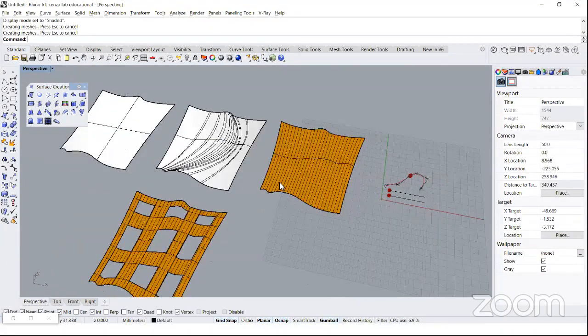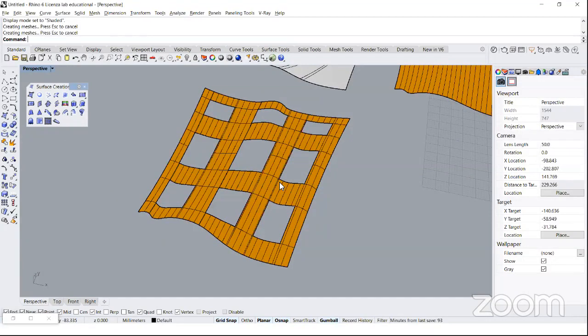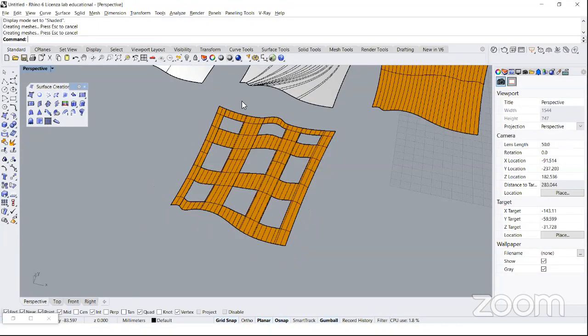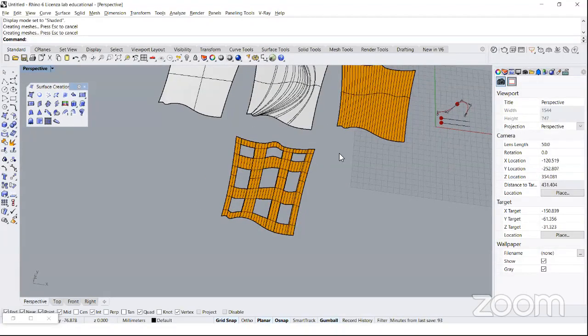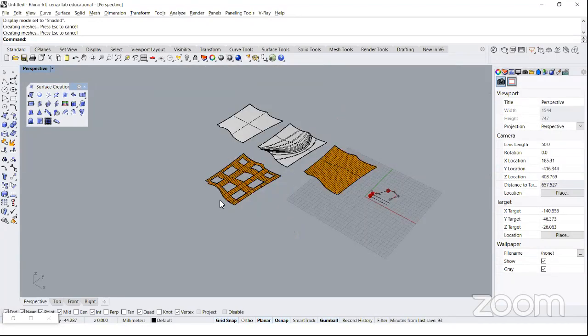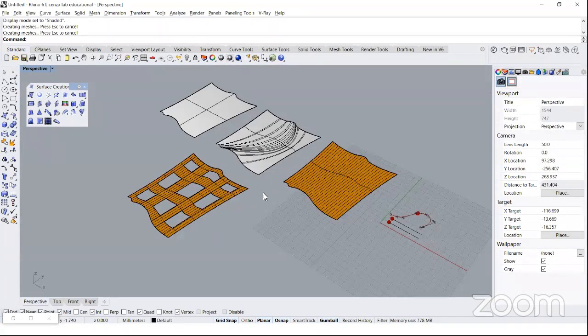One last consideration that I would like to do about controlling NURBS topology is this. You see that my surfaces are, well, either whitish or orange. Okay. This is because my Rhino is set to display the negative face of a NURBS surface.